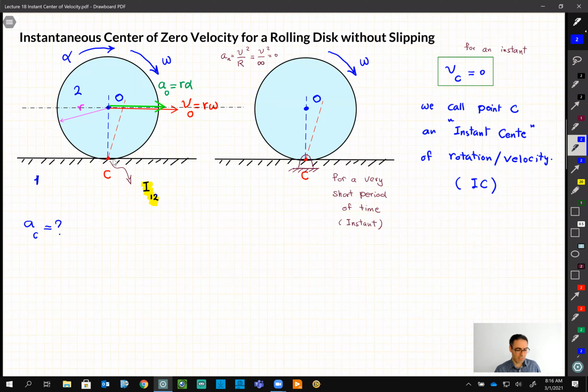It should be a curve motion. Try to imagine that you put, let's say, a point on this disk. Let's put this point here, like the one that I just highlighted in yellow. So this disk is rolling, and this point, for a very moment, at one time, comes and touches the ground. At that very moment, its velocity is 0, but this point keeps rolling, right? Its velocity at that very moment is 0 because everything is rolling about that point. But it's moving, right, on a curve.